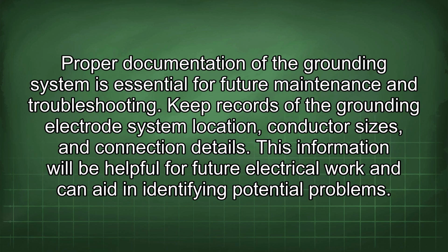Proper documentation of the grounding system is essential for future maintenance and troubleshooting. Keep records of the grounding electrode system location, conductor sizes, and connection details. This information will be helpful for future electrical work and can aid in identifying potential problems.